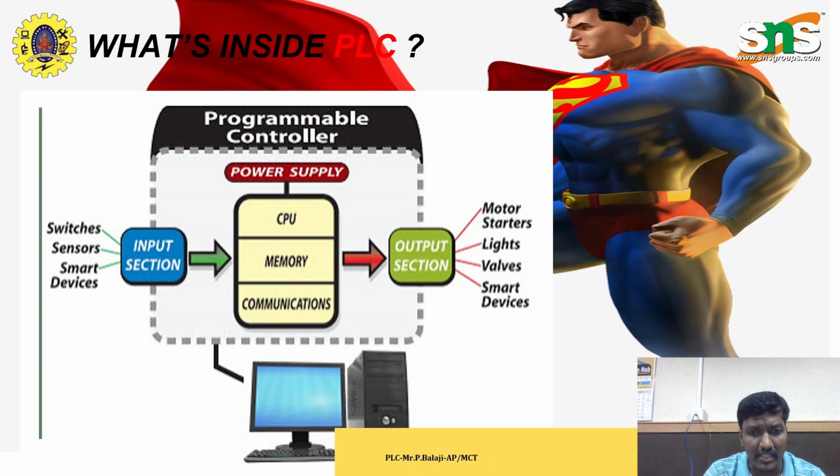Basically we have the PLC with communication like Ethernet, and we get input modules in digital mode and analog mode, and likewise outputs in digital mode and analog mode. We have 24 volt DC input to the input module, and we do uploads and downloads from the applications to the PLC through the Ethernet communication modes. We can also use communication buses like Modbus and Profibus for communication purposes. So these are the entire internal systems of the programmable logic controller.